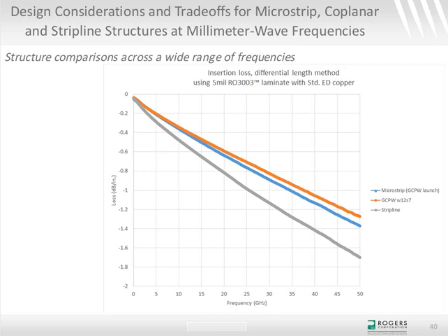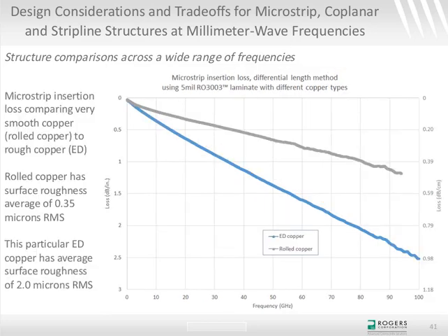And then the Microstrip is a straight Microstrip transmission line, except in the area of signal launch. So what I did was I used in-launch connectors for the signal launch, and just in the in-launch connector area only, I had a grounded coplanar waveguide. And I did that to help the signal launch, and it makes a big difference. So it is a microstrip circuit in the body of the circuit, but right at the connector signal launch, it's a grounded coplanar waveguide. So there you can see some differences of the three different structures using the exact same material, out to about 50 gigahertz.